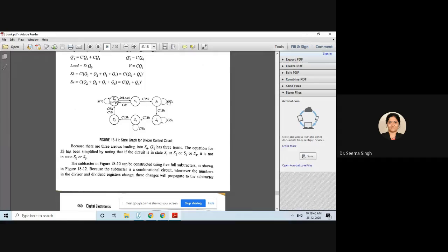I hope you remember that I told you in the beginning of the operation, before anything, shifting happens. So the shifting happens here. Then the comparison starts. If C is 1, subtraction happens, and also the same thing is stored as the quotient bit. And if C is 0, only shifting happens. So what you can see, if C is 1, subtraction happens here, and after that shifting happens. If C is 0, it will not go to this state. It will directly shift only. I hope you are understanding. There are two possibilities. One is subtract and shift. The other one is only shift.